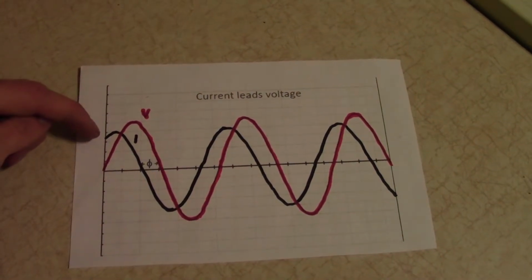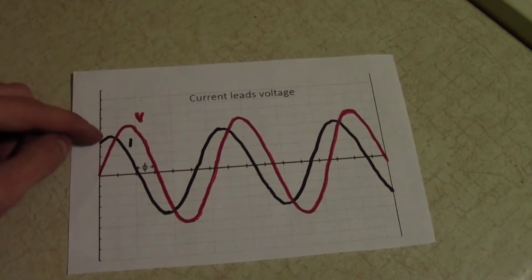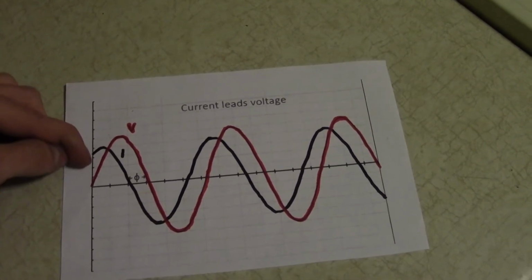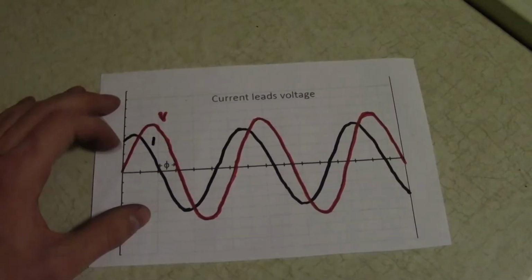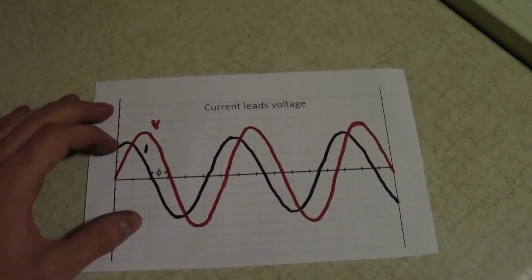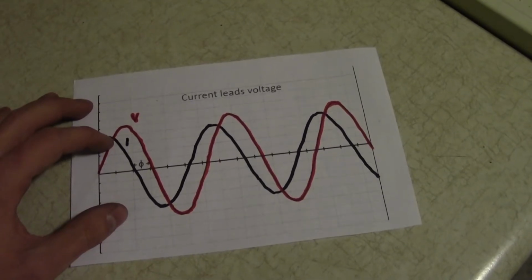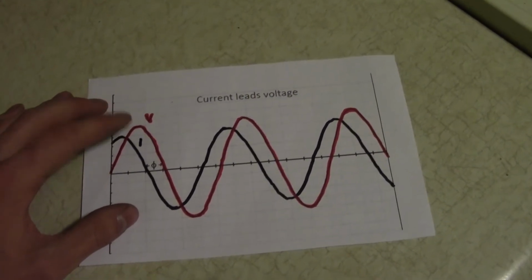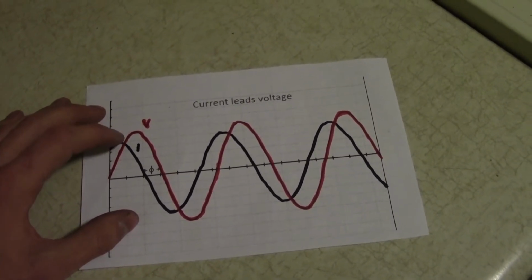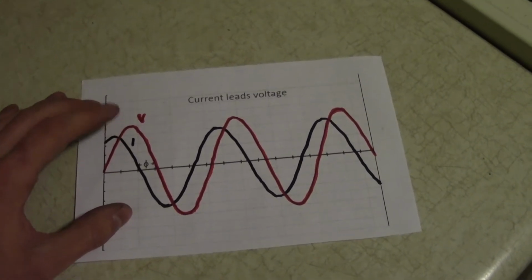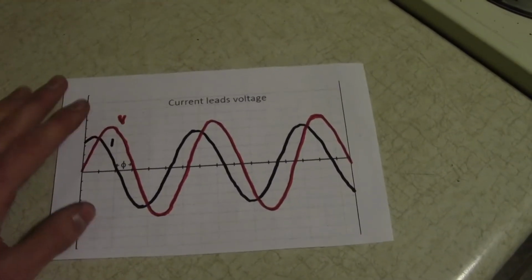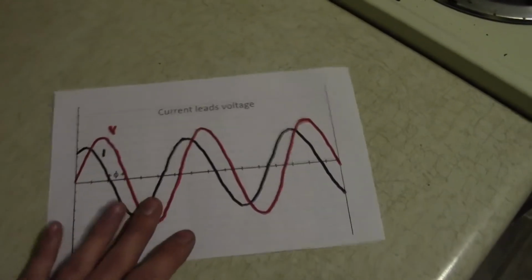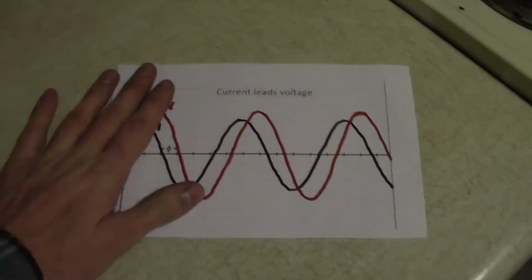Just a quick note, it is possible that my potentiometer in series with the capacitor won't work because the capacitor will not reach capacitance. It will limit the current flowing to the capacitor. Part of the reason I think this current peaks here is just because the capacitor is approaching fully charged. If you had a resistor in series, it would limit the current going to the capacitor, but the capacitor would not be fully charged. So it would take the maximum current allowed by that resistor for a longer period of time. So yeah, that might not work. That might make my graph totally weird, and it might not function as a power factor correction. I don't know. I'm going to have to see.